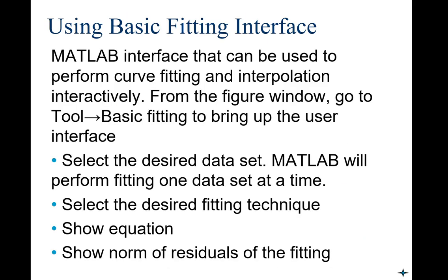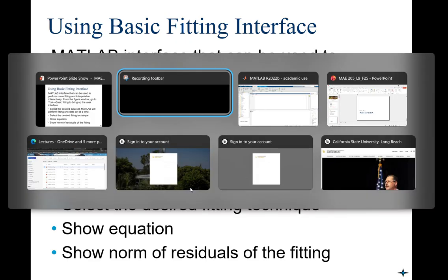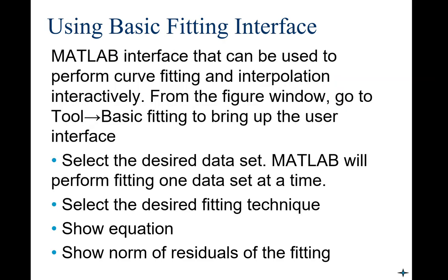MATLAB also has some tools. So instead of hard coding these interpolated lines, you could go into your figure window when a chart gets generated, click on Tools, Basic Fitting, and there are options in there for putting in a specific curve or regression line. Let's look at an example. Let's see if we can actually repeat the same equation.